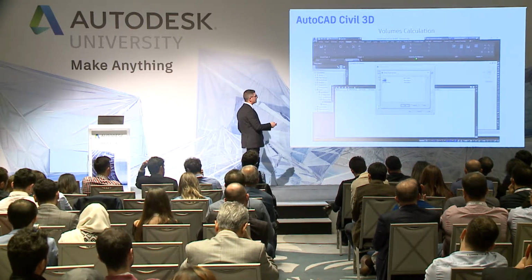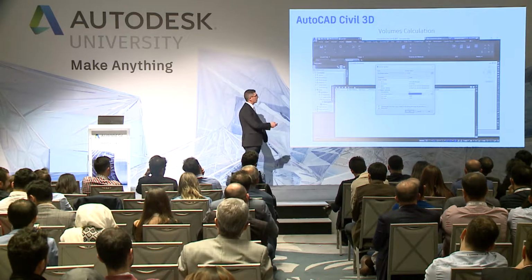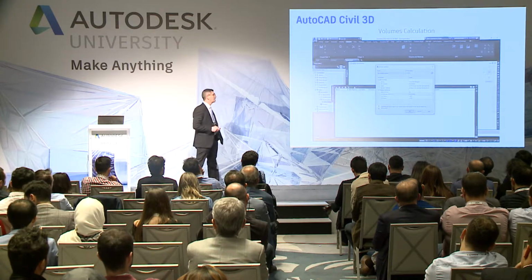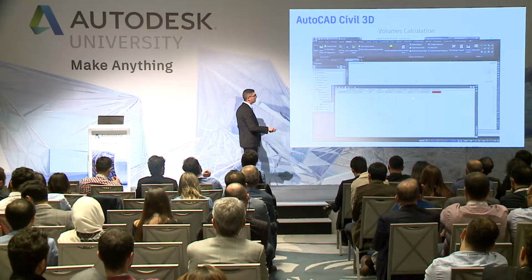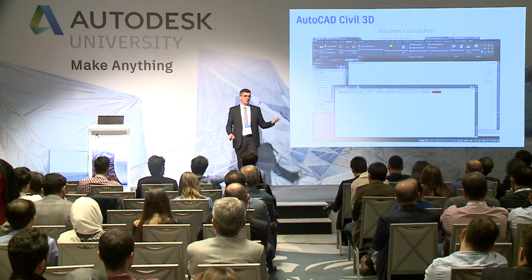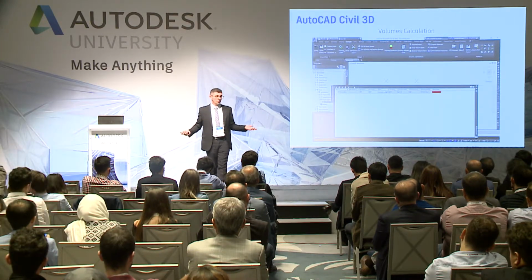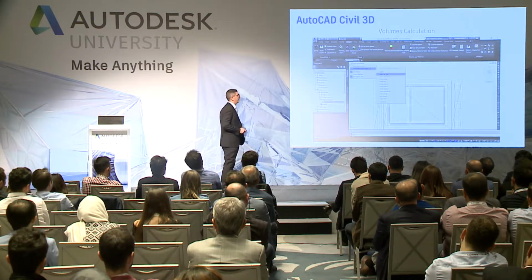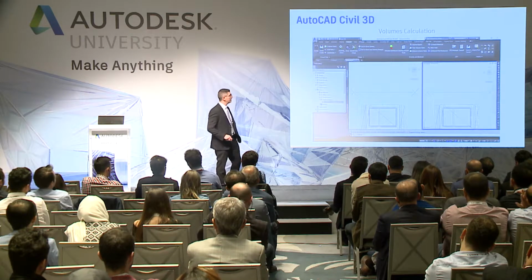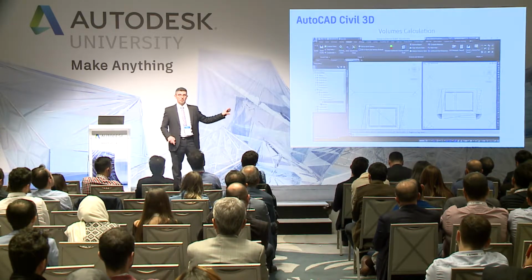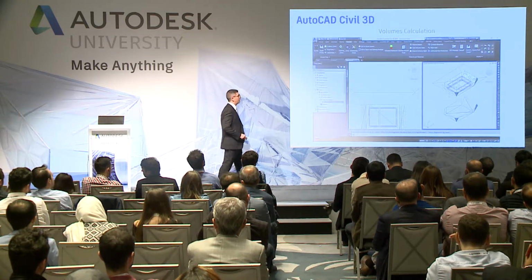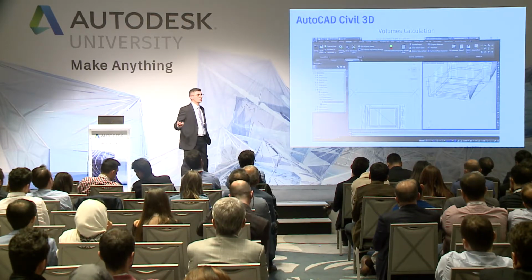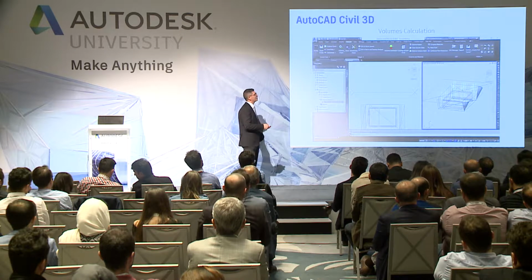The base surface for the calculation is the existing ground, and the second one, the comparison surface, is the volume surface. Then I click on OK, and in my row, I immediately have the volume of the calculation with the difference between cut and fill. In this case, we only have cut. These models are dynamic. If you change something, you immediately have the update of the model and the calculation of the element. This element is a calculation of Civil 3D, OK? It's not for managing the design.